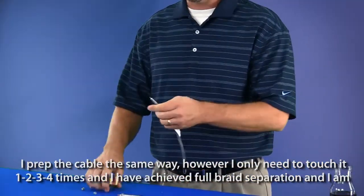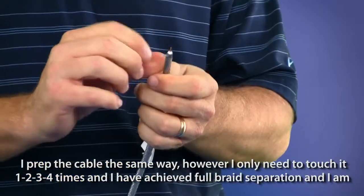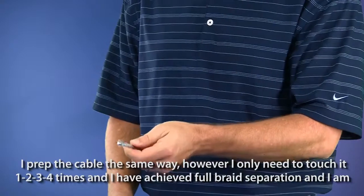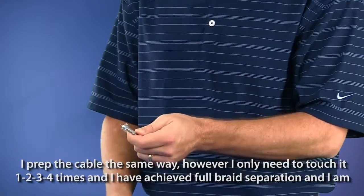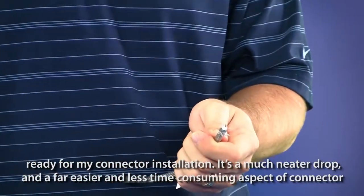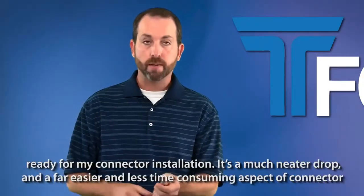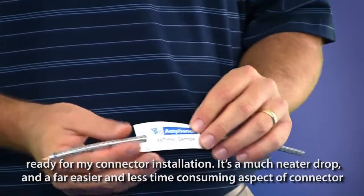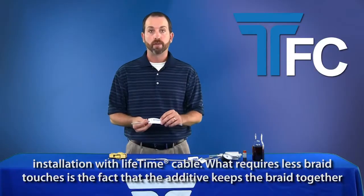As we'll notice, I prep the cable the same way. However, I only need to touch it 1, 2, 3, 4 times, and I've achieved full braid separation, and I'm ready for my connector installation. So it's a much neater drop and a far easier and less time-consuming aspect of connector installation with lifetime cable.